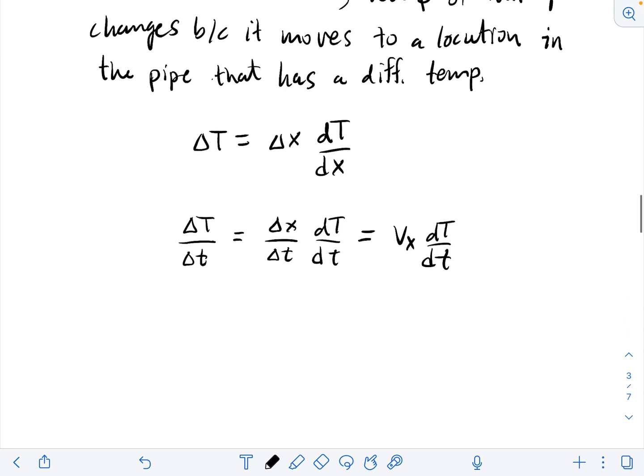Now we've thought of only a one-dimensional problem, but we could have, say, a cube filled with water, and then we pick a fluid particle within that cube, and there's some complicated temperature gradient that goes in some arbitrary direction. We would have terms like this for the x, y, and z directions, and in general what we would find is that the time rate of change of the temperature of the fluid particle due to its motion would be given by this expression.